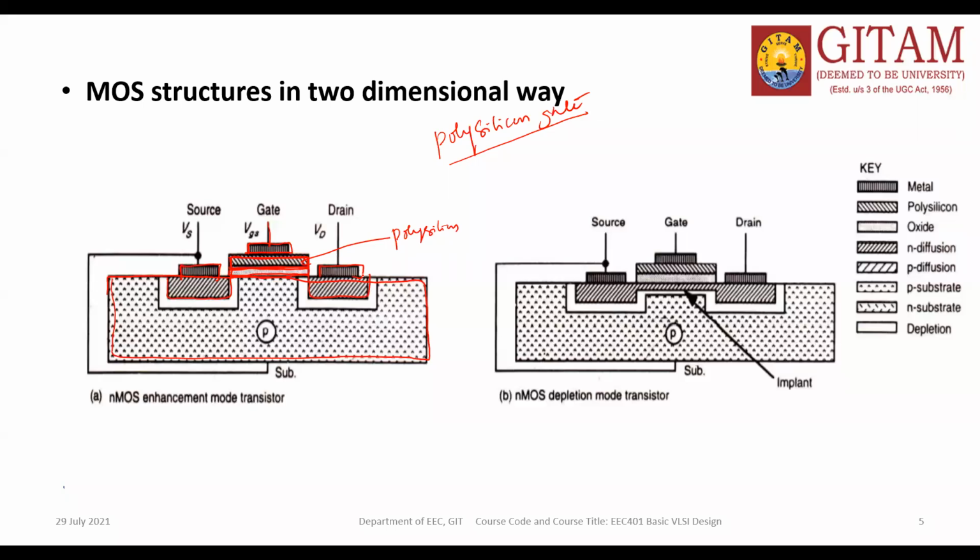So why have they introduced these spaces here? What does this space belong to? This is actually a depletion mode type of depletion charge, or space charge, we can call it. Normally, for example, we have a p type substrate here. Whenever you diffuse something inside of this, at the edges of this particular diffusion, electron-hole recombination takes place.